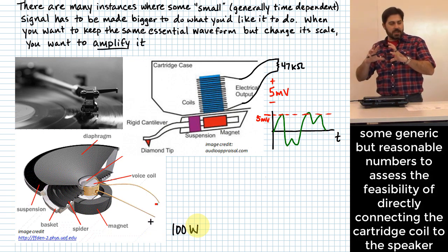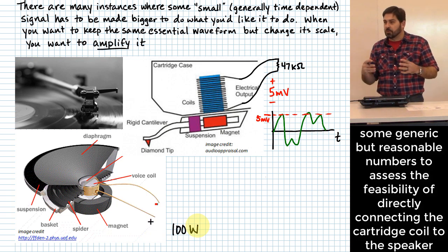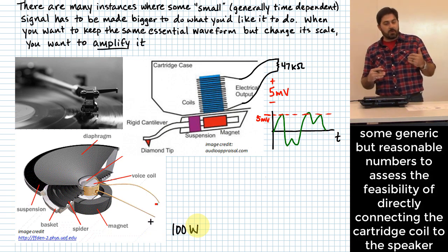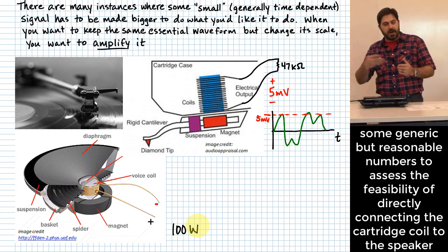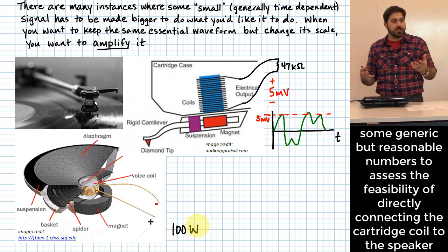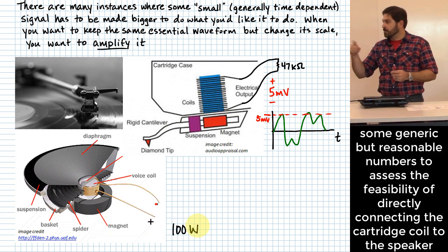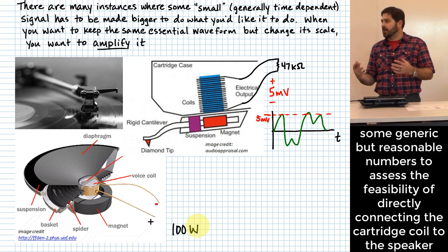There's this thing we're going to get into a little later in the course called the root mean square voltage of that wave. The impedance is something where if you take that root mean square voltage of a signal wave and divide by that impedance, it gives you about how much the current is going to be flowing in that wire. Okay? So we can treat impedance like it's a resistance is basically the takeaway from that.